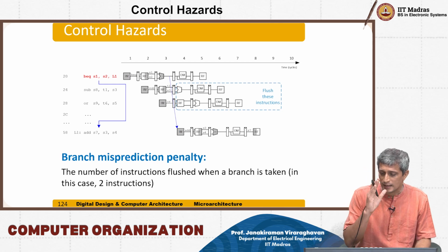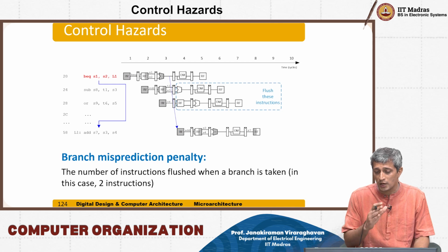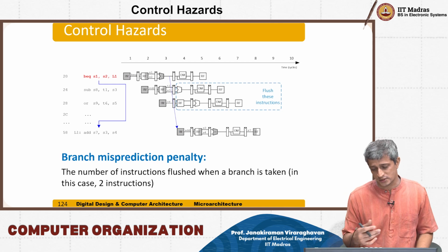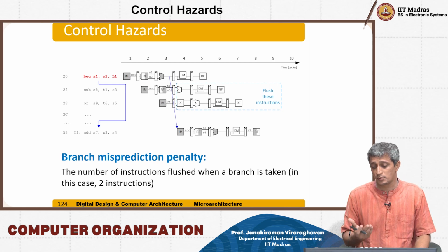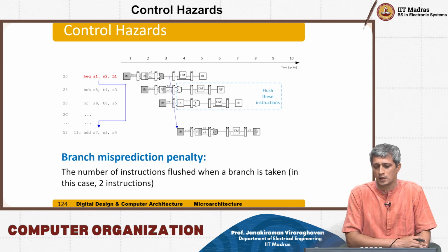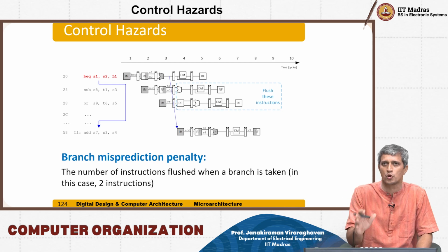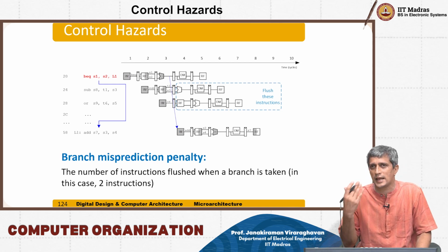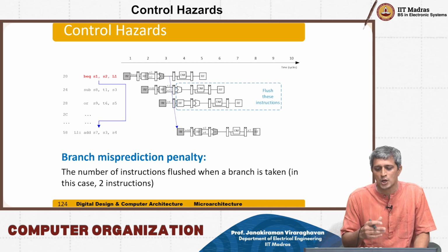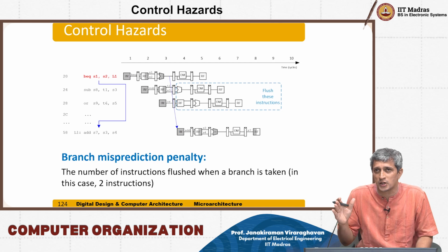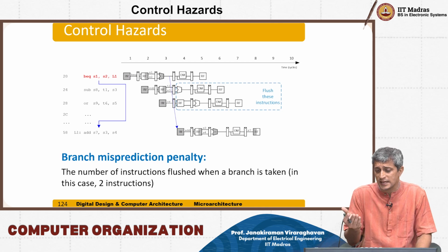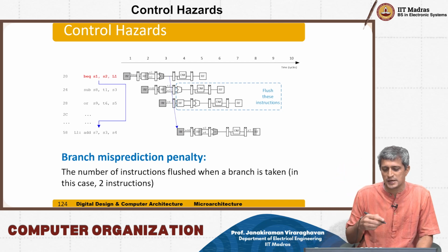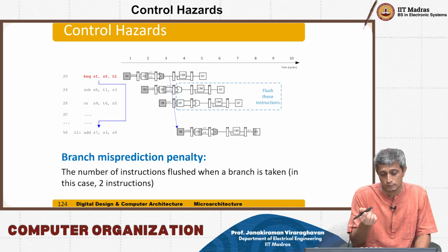So the point is that in clock cycle 3, what you really have to do is to figure out that the 0 flag has got set, which means I cannot go ahead and simply execute this subtraction or this other instruction. You have to prevent the execution from happening. It's okay, you have prefetched it, you have decoded it, but do not execute it, because then a lot of things can change. So you have to basically flush these instructions, and instead the new PC, the value that you have calculated, you need to get it from there.